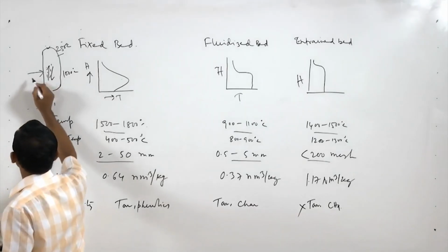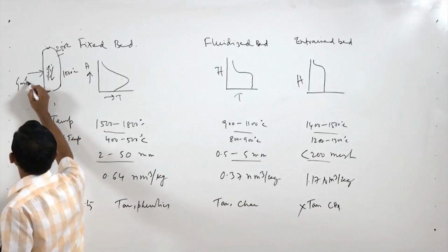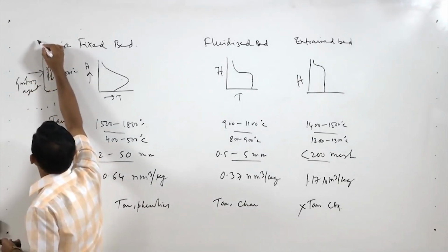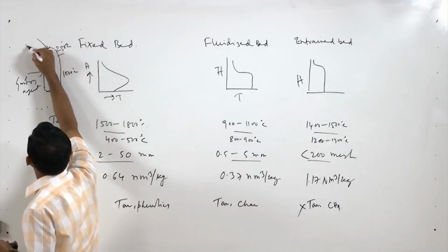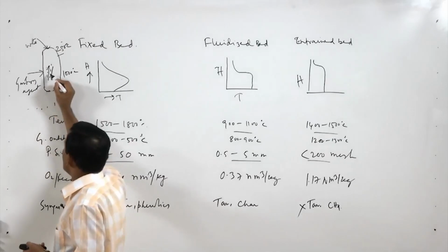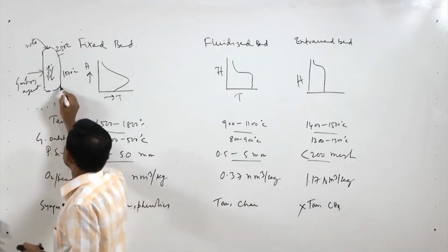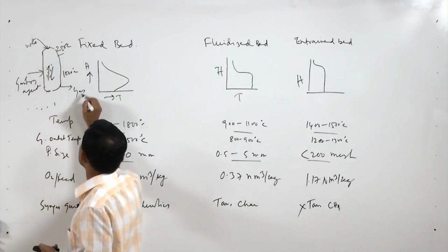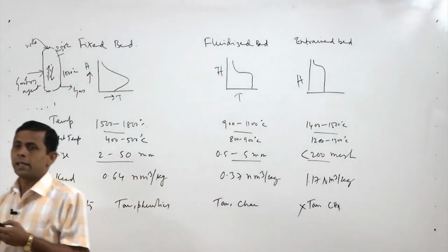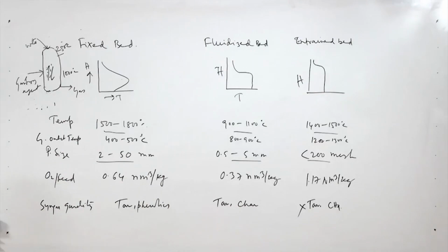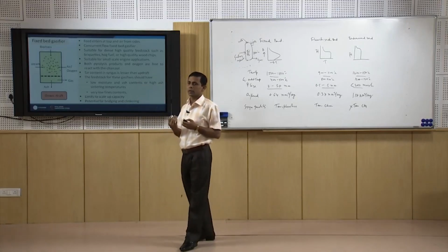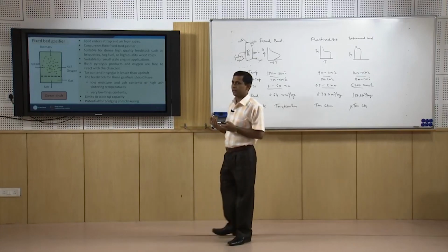So, here we are giving the gasifying agent and here the waste or biomass, and we are collecting syngas here. So, the material and gasifying agent flow parallelly inside the gasifier and get more chance for contact and reactions.